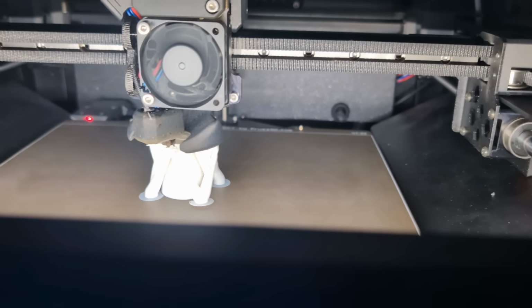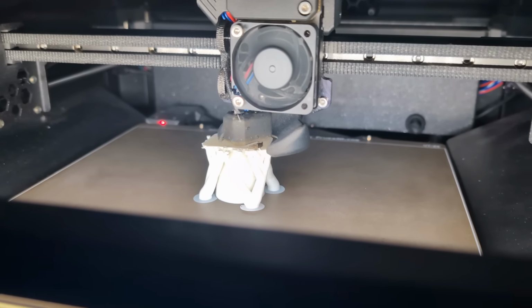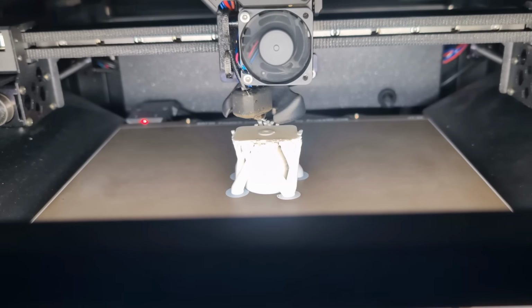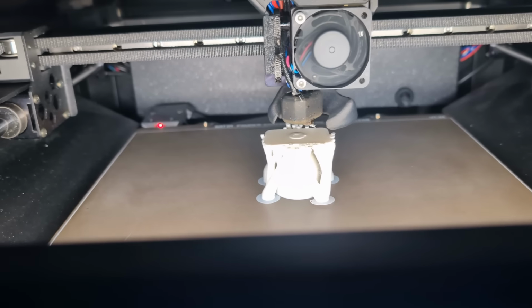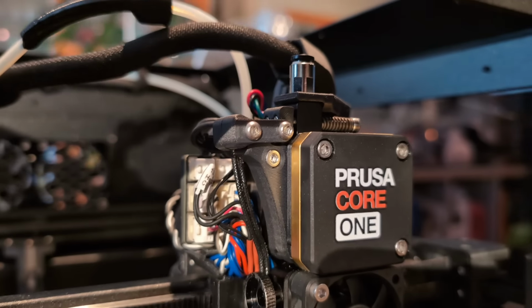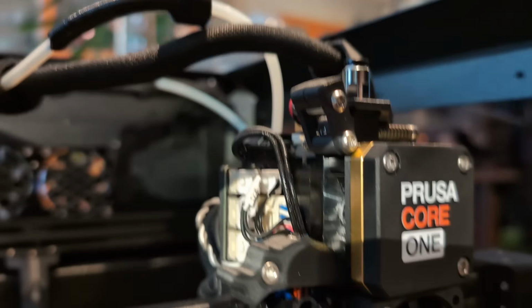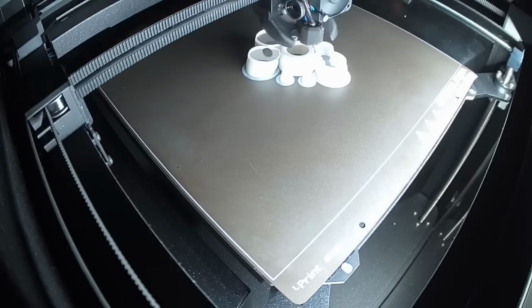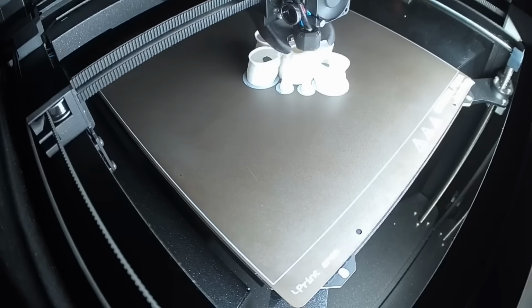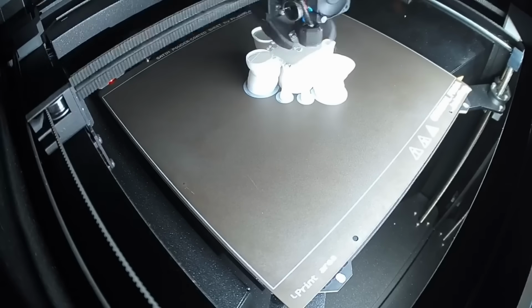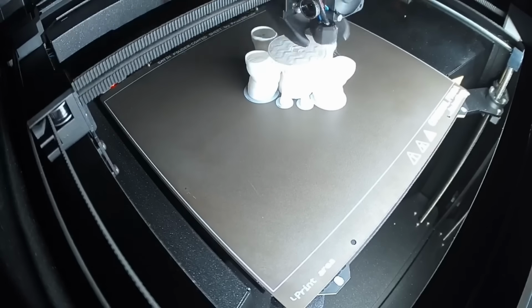And I first blamed the mod, but of course it was not the mod's fault, it was the filament that broke inside the nozzle. So that was another whole ordeal. I had to disassemble the nozzle and I wasn't able to push out the filament, so I had to heat it up until it was a little bit softer, and then it kind of ran out, and then I pulled it out, and anyway, another hour of work until I got my printer working again.